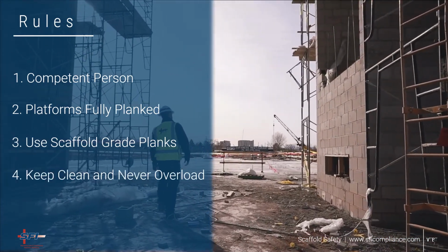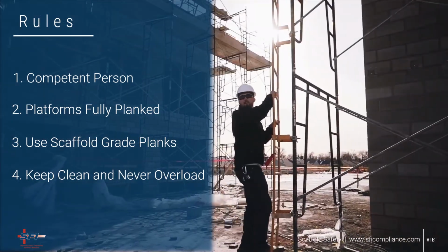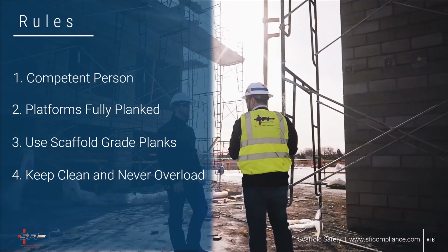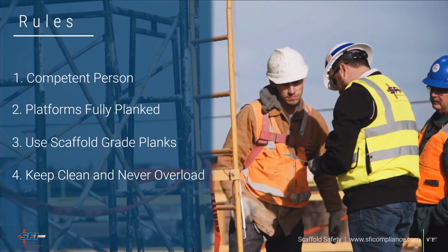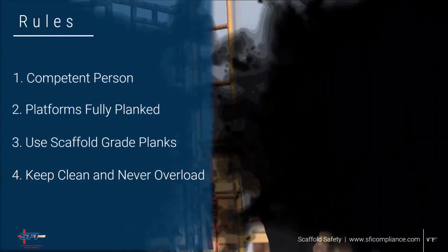Don't stockpile materials on scaffolds. Remove all tools and leftover materials at the end of the day. Never overload scaffolds. Pile necessary materials over ledger and bearing points. Keep platforms and area near scaffold clear of debris, unneeded equipment or material, and anything else that might cause you to slip or trip.